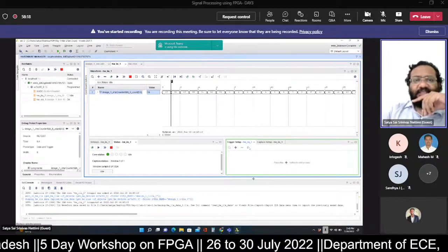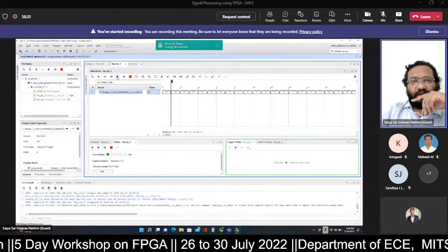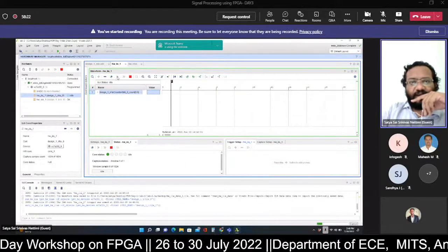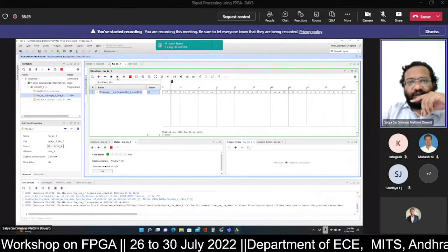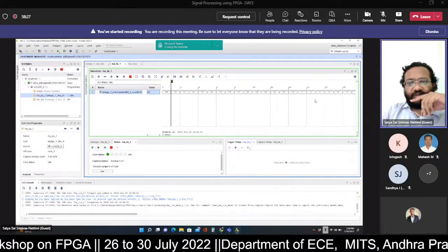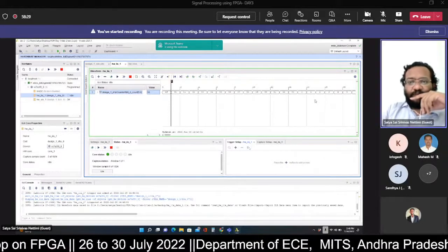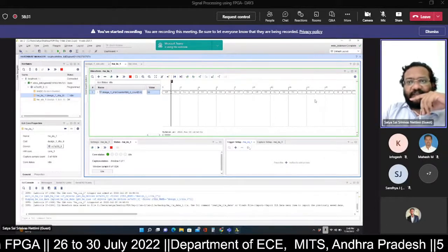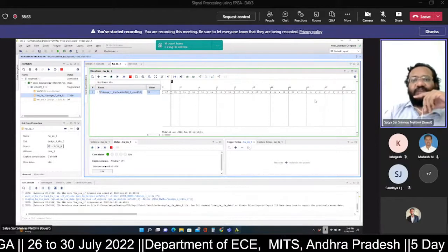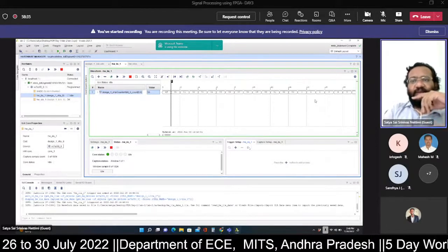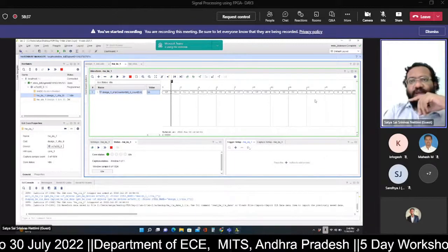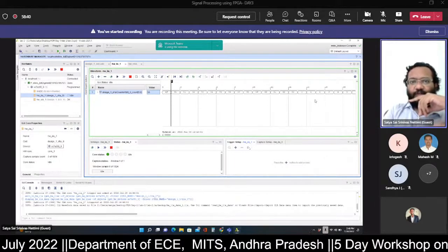In this case, this is of a normal random nature. You are just running the trigger randomly, and at that instant, whatever output is there at that time is captured. There is also provision for you to give conditions. When this condition is happening, then only you capture the data. At those conditions, you can check how the hardware is responding and how the output is generating.